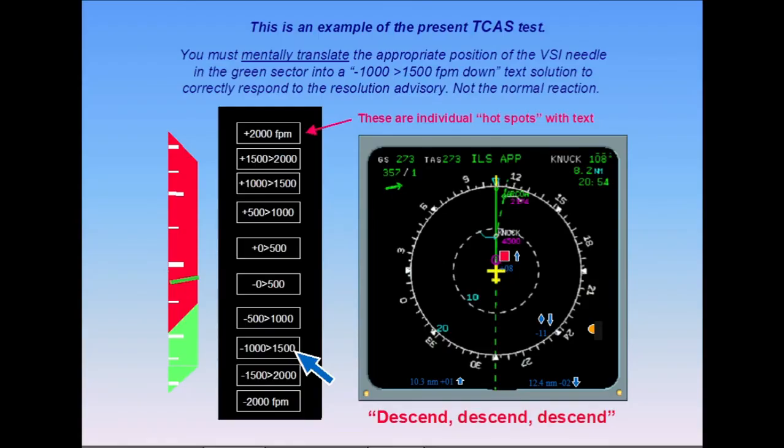You must select the correct action in response to the TCAS advisories and commands. Answers are made by choosing the correct vertical speed response from the selections available to the right of the vertical speed tape on the computer display. Your response time must be less than the 5 or 2.5 seconds required by the scenario and the type of vertical command involved. You may miss only 3 questions. If you fail the test, review this presentation and ask the office personnel to reset the program so you may try again. Clear of conflict.